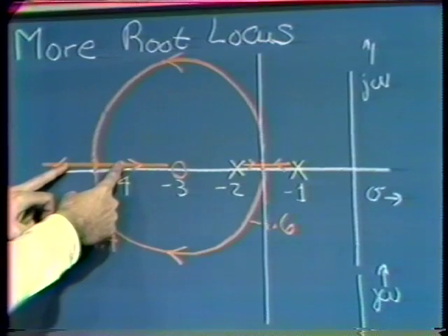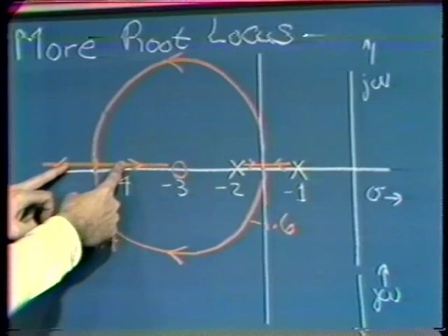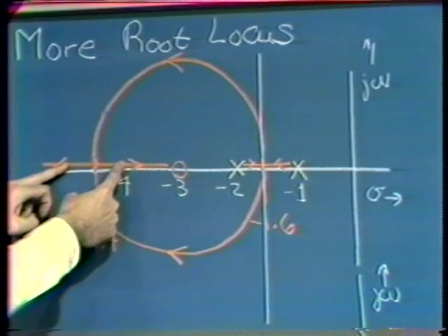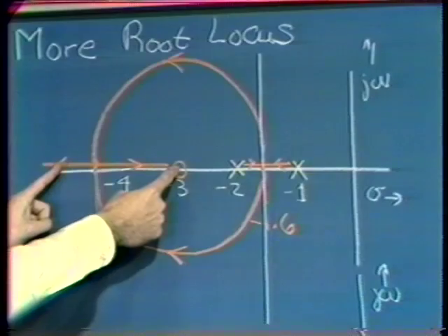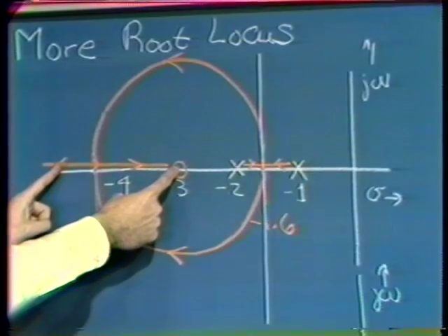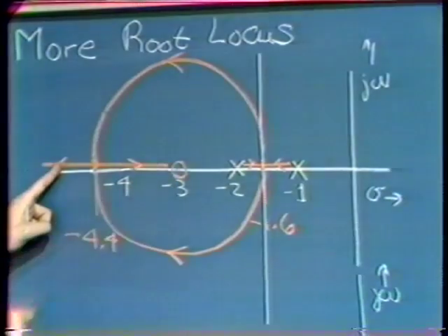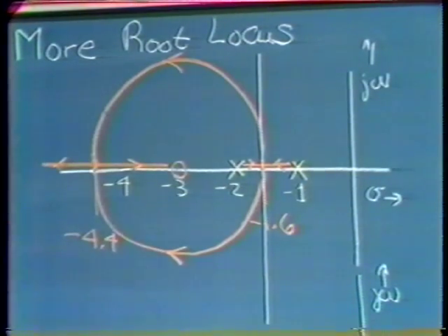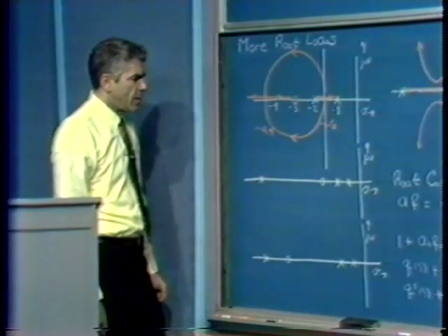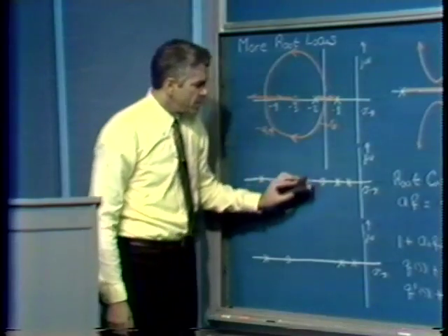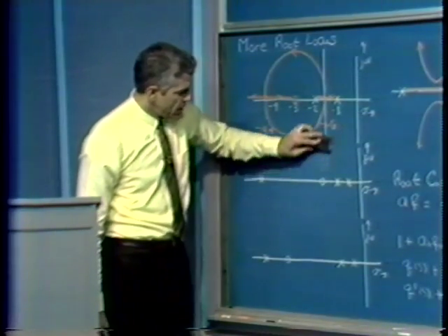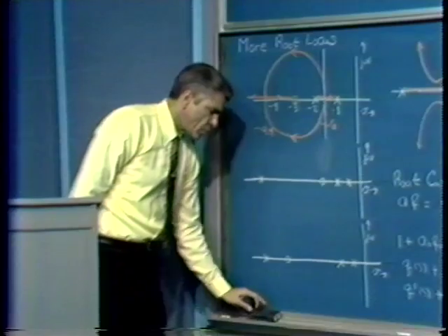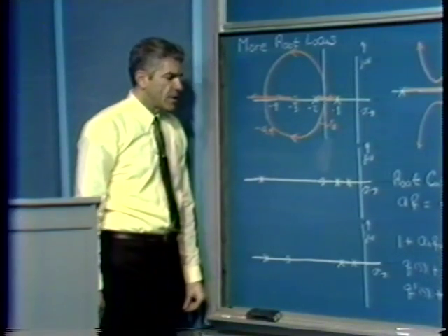And so now we have the overdamped situation. We have no overshoot at all in the step response, no peaking in the frequency response. So the important point is that adding the 0, assuming we're able to do it in view of other system constraints, allows us to get much higher values of desensitivity, much larger A naught, F naught products without running into any stability problem. And that theme continues for many, many other loop transmission pole 0 configurations.